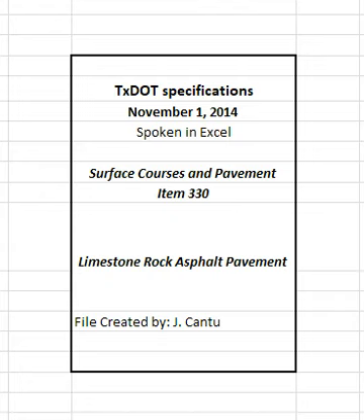Apply a thin, uniform tack coat to all contact surfaces of curbs, structures, and joints. Prevent splattering of the tack coat when placed adjacent to curb, gutter, and structures. Roll the tack coat with a pneumatic tire roller to remove streaks and other irregular patterns when directed.